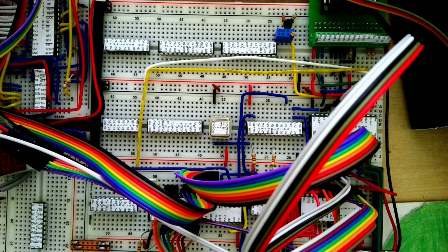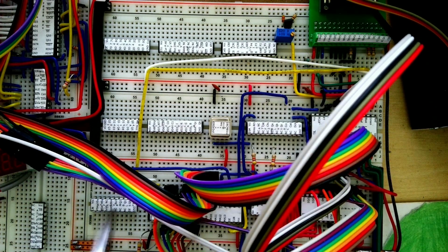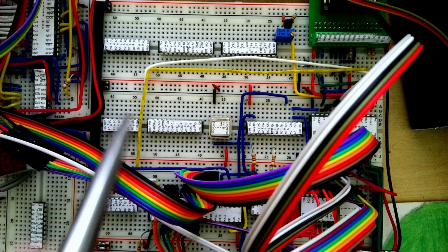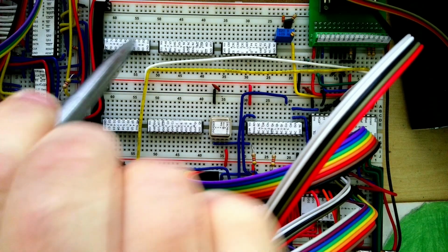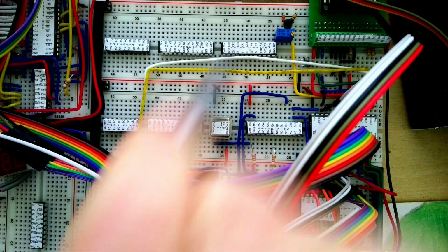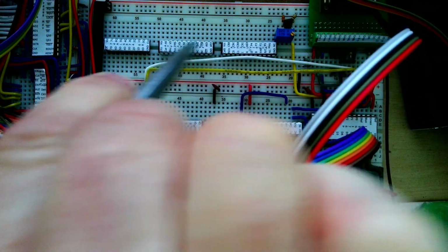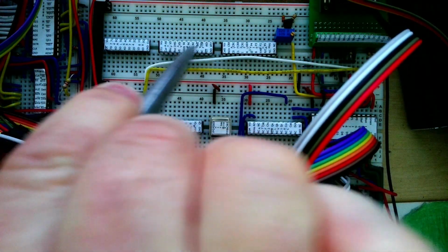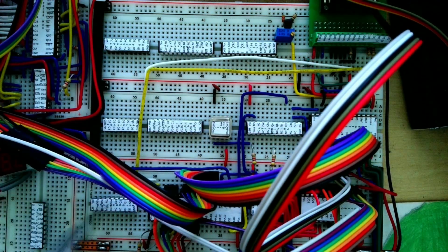So this is the region of the board. This is the blink PLD down here. This is the mode control port and color register. Then we have the attribute latch multiplexer here, and the final output video PLD here, and this is the one that does the text mode, cursor blinking, and all that sort of stuff. So we're going to need to hook up all of those.